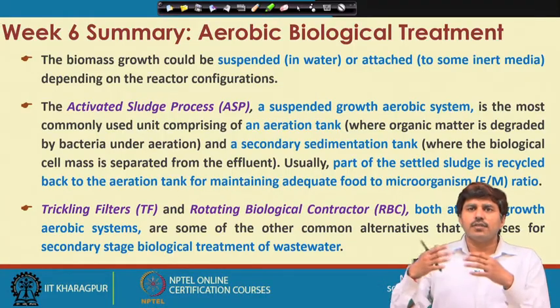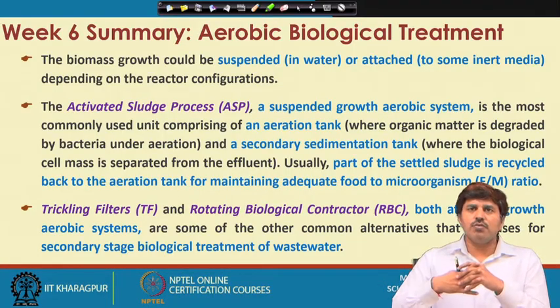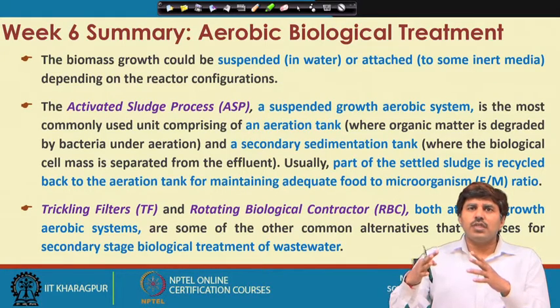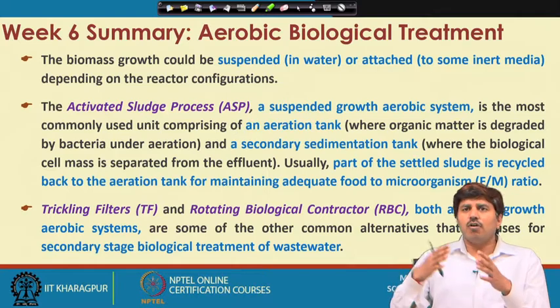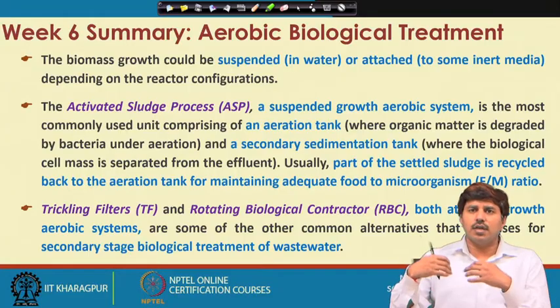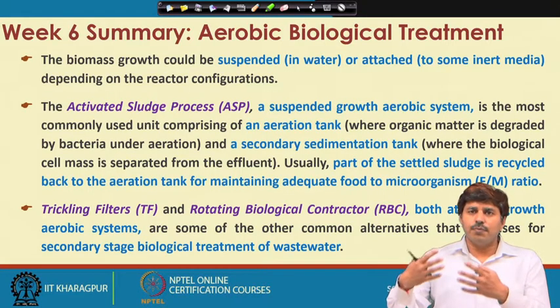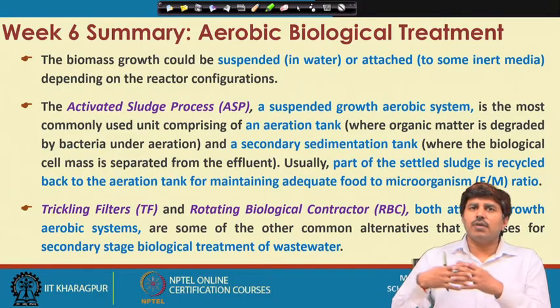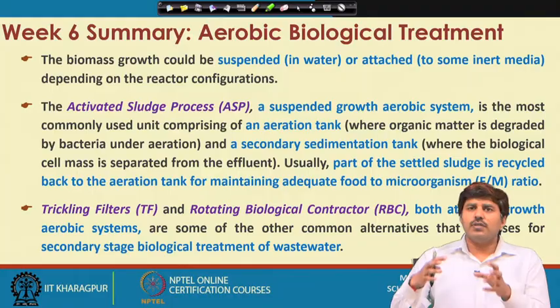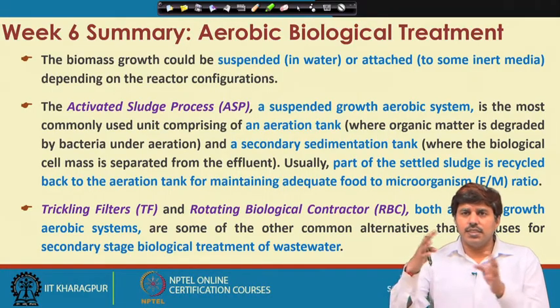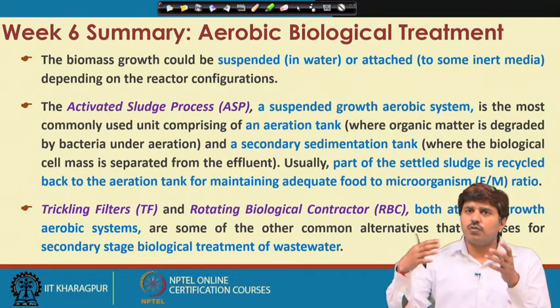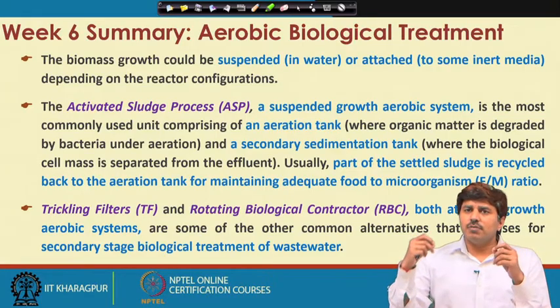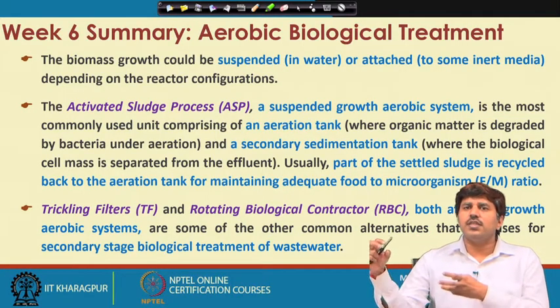byproducts, and could actually form some gases also like CO2, but it also produces a lot of biomass in the process. In the aerobic system, almost 40 to 50% of the organic carbon which is decomposed is used for converting into biomass. So, a lot of biomass is generated, and since it is a suspended growth system, the microorganisms remain in suspension, and when the water is taken from the aeration unit,